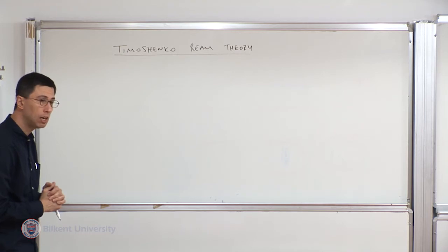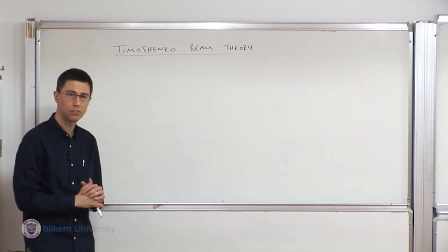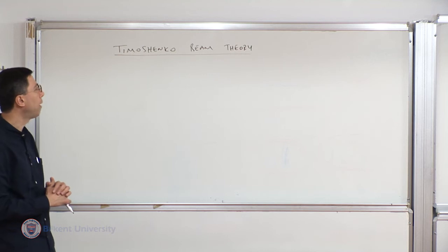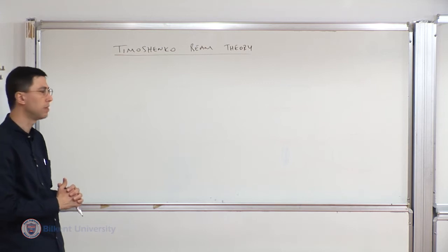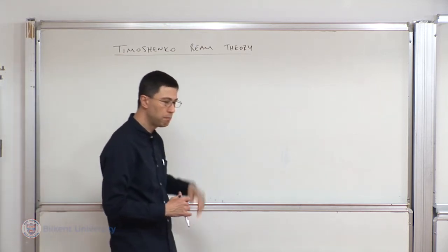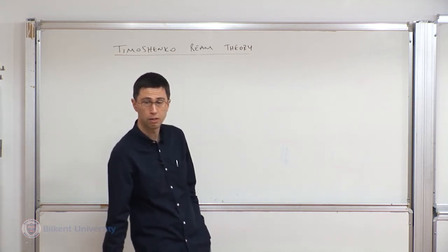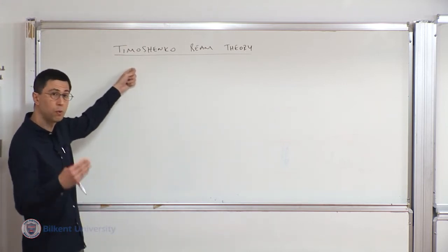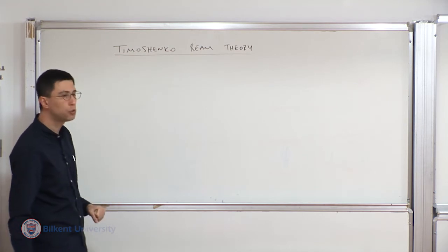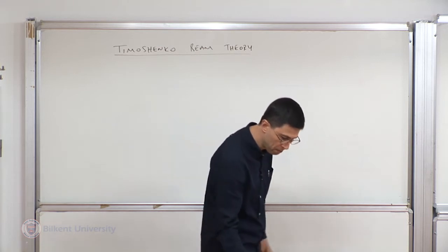And eventually, in light of the exact results that we finished deriving last time under the cantilevered beam topic, we're going to go back to a very fundamental theory, the beam theory, and we're going to improve that theory. The fundamental beam theory that we had covered in ME 231 was called the classical or Euler-Bernoulli beam theory. I will highlight a few shortcomings in view of the exact results that we obtained, and we're going to improve it one step ahead under the name of the Timoshenko beam theory.